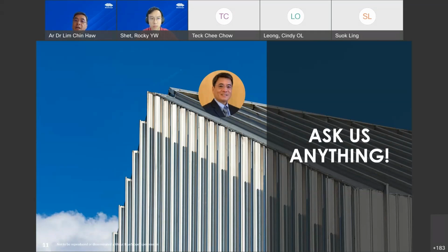Also the finishing and the insulation: certain concrete flat roofs also provide insulation, for instance bitumen, or even the torch-on membrane that you put on, which will also affect the U value of the roof. So I think it all depends on the configuration of the roofing system. There's no standard generic R value or U value for either of these roofing systems, I would say.